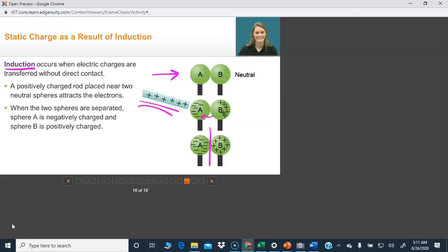So somehow it has to have a way to transfer electricity from the part of the fan that's not moving, called the stator, to the part of the fan that is moving, called the rotor. That's a relationship between electricity and magnetism that causes that to happen. We'll get into that later, but the point to be made here is that the electricity coming from the wall is creating an induction effect in the part of the fan that turns.